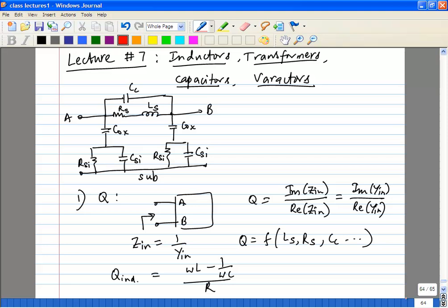So in general, when you want to design your inductor, you want to use a higher metal layer, okay? Typically the highest metal layer you have access to would be the one you would start off with. Then you might end up using the next metal layer. We saw last week there are cases when you want to connect to both the ports, you will always need an underpass, so you may use the next layer for an underpass, okay? Or, if the next layer is also a thick layer with low resistivity, you may use a combination of both the layers to create a very high Q inductor.